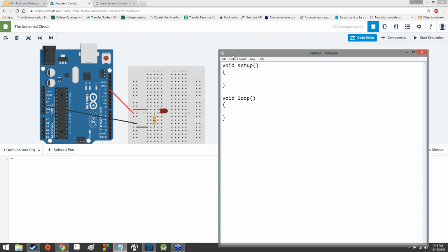Okay. So functions, those are a thing. Before we mess around with functions at all, though, I'm going to add one thing. This is our first command in programming. int space LED capital PIN space equals space 13 and then a semicolon. The semicolon is not a typo. Semicolon is kind of like the period at the end of the sentence.